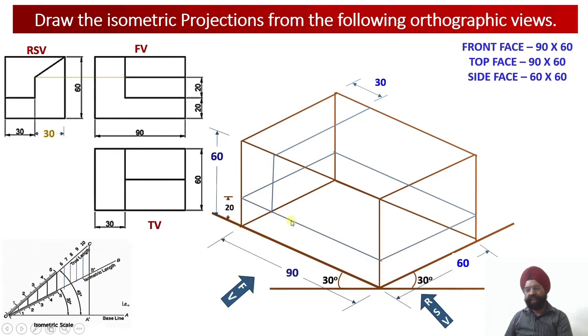So we have constructed this particular vertical face and this horizontal face over here alongside element number 1. Why? Because you can see over here in the front view, I am able to obtain this L shape. So now I am going to carry out the breakdown of this total element. That is, this total element is this one. That is, at the bottom 60 millimeter it goes straight. So 60 millimeter it will be going straight.